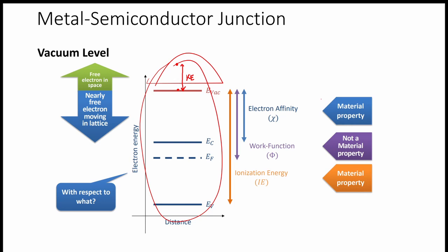This is the semiconductor. In a semiconductor there is a conduction band, a valence band, and the Fermi level. This is an n-type semiconductor. As you can see, this Fermi level is closer to the conduction band, so this difference is lesser than this difference. Since it is closer to the conduction band, this is an n-type semiconductor.